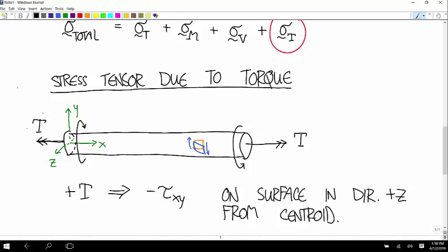But if you draw that arrow on the parallelogram, it would be on the y. Yes, it's in the negative y direction. But think of that orange thing as the front of a stress cube. The face that this force is acting on is the right side, the positive x face. So it's on the positive x face in the negative y direction.